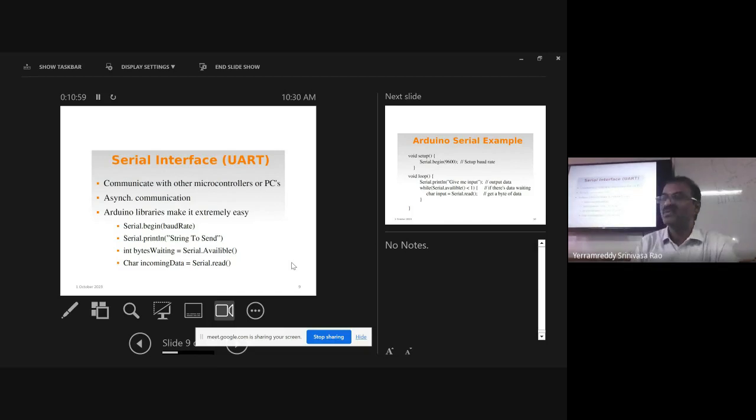Whatever there is on the screen, only that we will be doing, because we want to work with the mathematics. We want to work with the data types. So when we want to do this, somehow we should be able to enter the data and read the data. For that purpose, we are using this peripheral of the CPU, which for us is the standard input output. In our case, standard input output means serially transmit, serially receive. In a computer, standard input output means your ASCII keyboard and computer monitor is your stdio. But here it is serially transmit, serially receive.